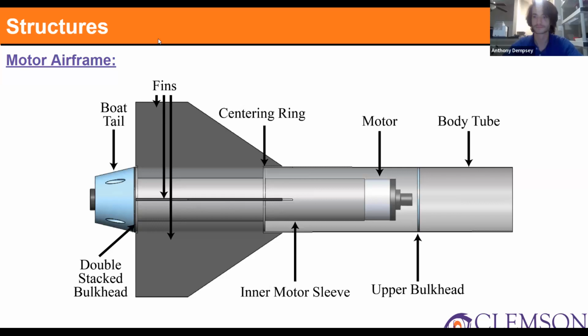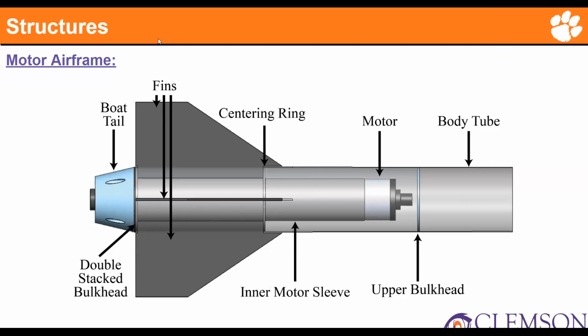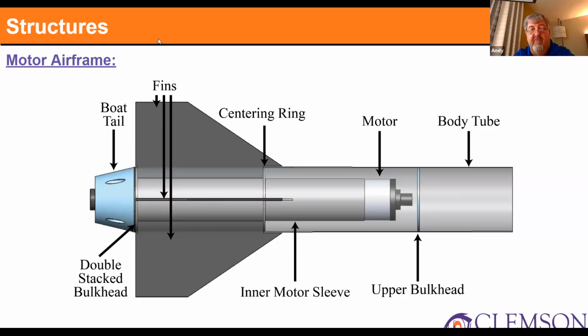So in future designs, if you think about it, you can't get a better anchor point than putting an eye bolt to the top of that motor case. Let's say, for instance, the whole rear end of that rocket shredded, and the motor case was free to fall wherever it wanted to. If it's got an eye bolt going to a shock cord going to a parachute, then you'd have little thin light pieces of your fin falling to the ground, but that very heavy metallic motor case, more than likely, hopefully, still under some form of a parachute.